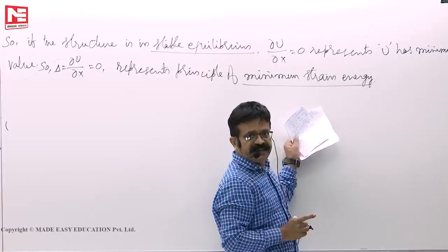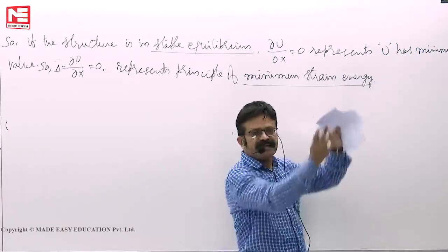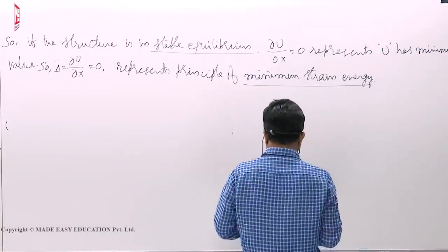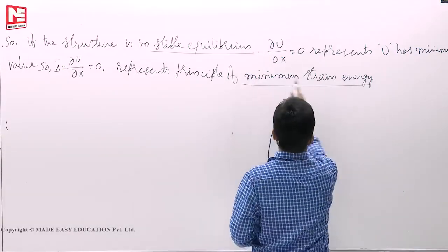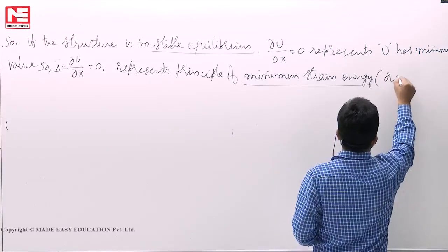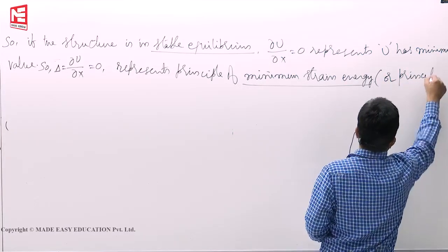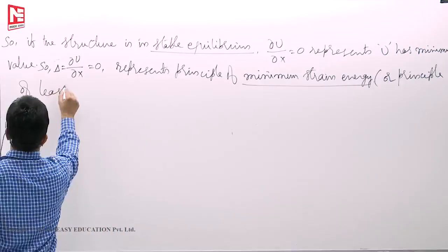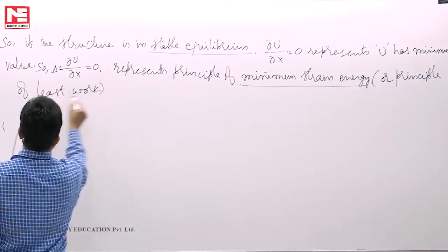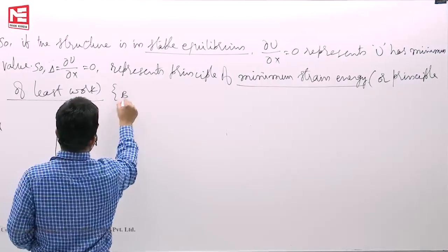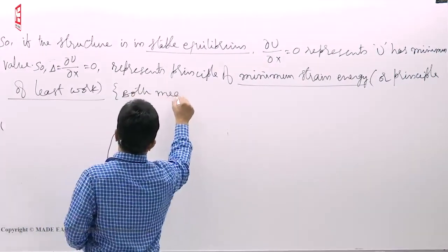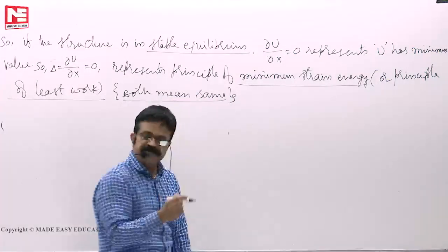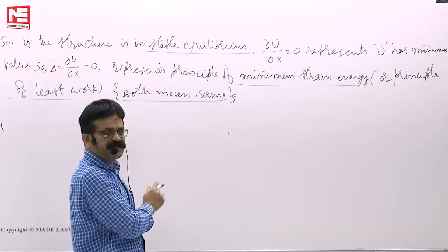That means minimum strain energy and minimum complementary energy come under force methods of analysis. Sometimes you call the principle of minimum strain energy the principle of least work. Both mean the same.